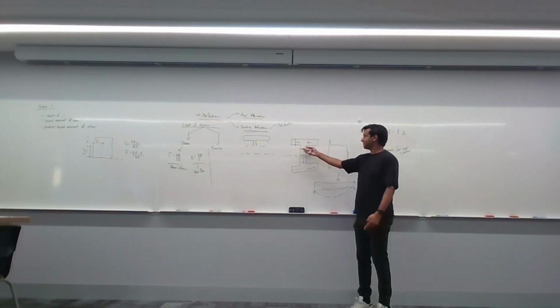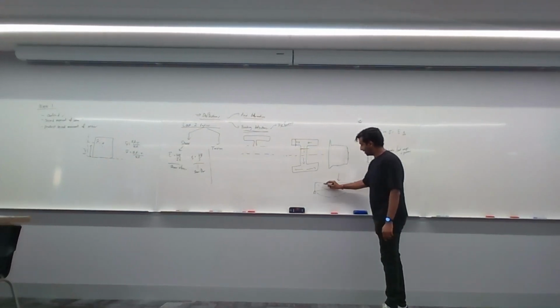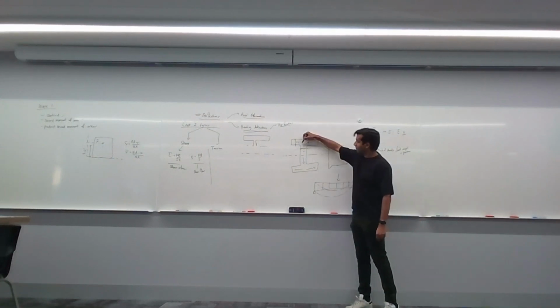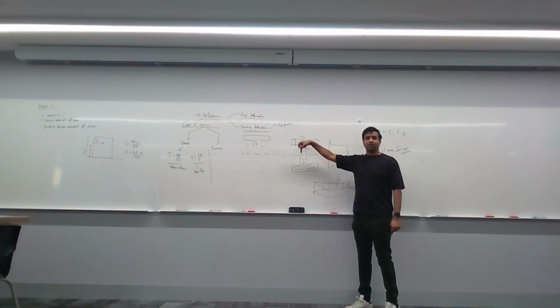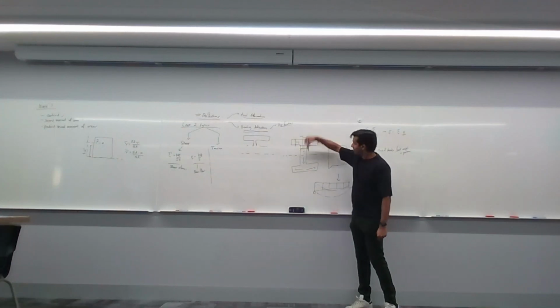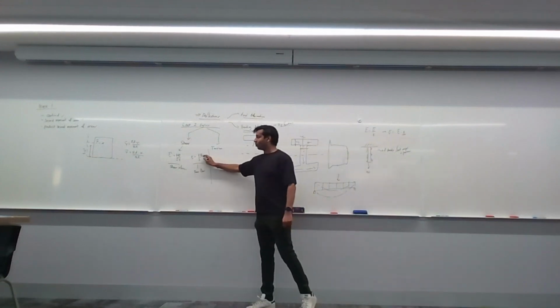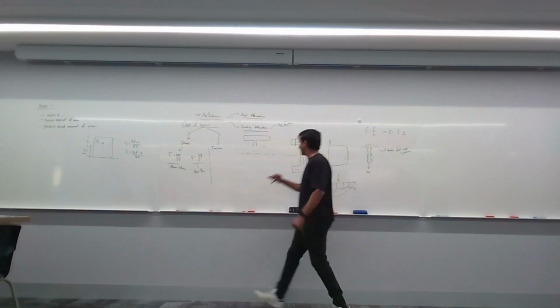Because let's say I've got 5 nails that I'm applying to the beam, those nails are all, let's say, here, like that's a nail, right? The direction I'm interested in is into the page, because I'm going to be nailing 5 nails into the page, at different spacings. So remember, VQ over I calculates the shear flow at a given point.